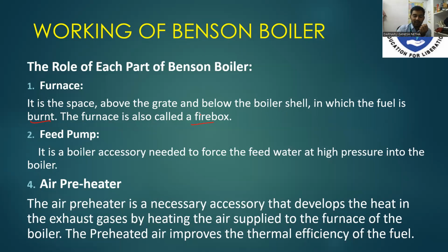Feed pump. What is the function of the feed pump? The feed pump is to send the feed water at high pressure. And in the first slide we discussed Benson boiler is a high pressure boiler. So that is the reason the feed pump is required, because we need to pump the water by forced circulation. That's the reason the feed pump is required.